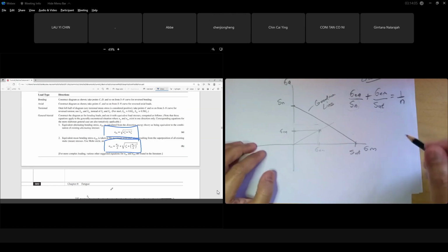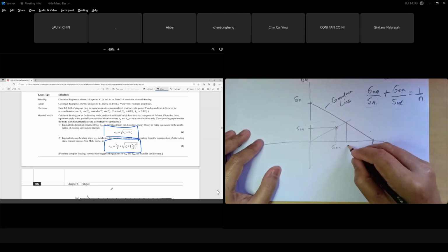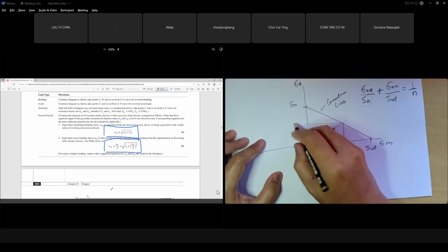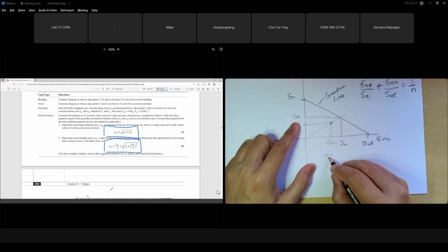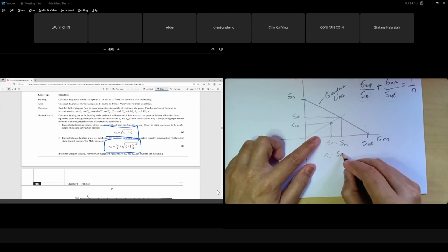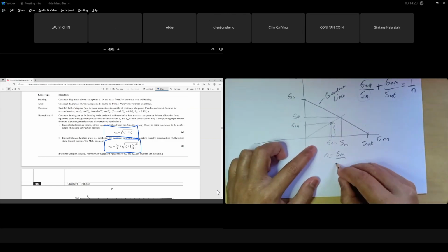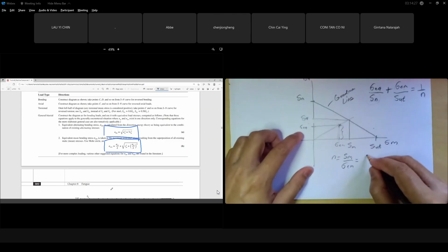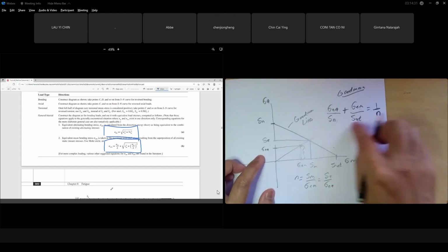Okay, or you can use the graph. Here sigma EM, you go for this. So this one becomes SM, you can also use it if you don't want to use the graph. This one will be your strength amplitude. Your safety factor is, you can also use the graph, your SM over the value of your sigma EM. Also the safety factor is your SA here, SA over your sigma EA. Same value as you get from this one.